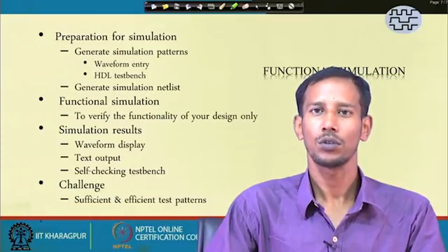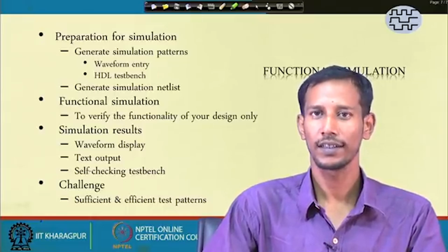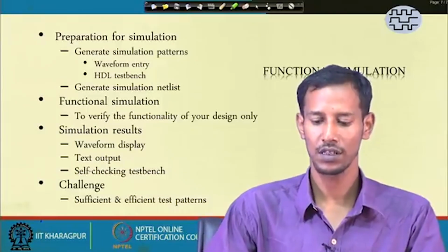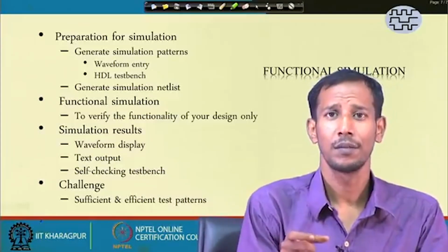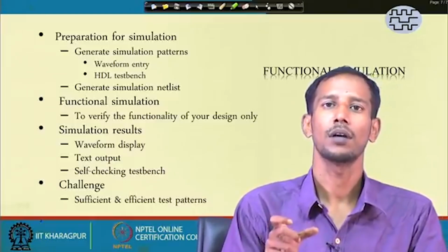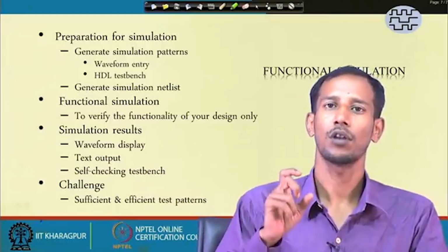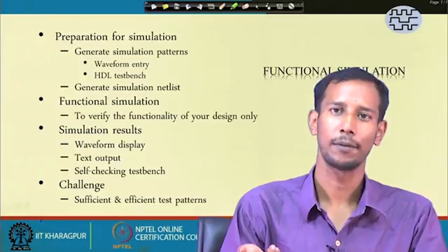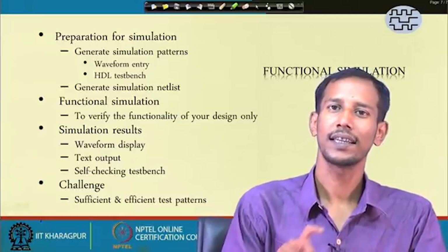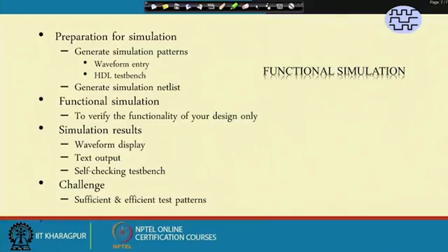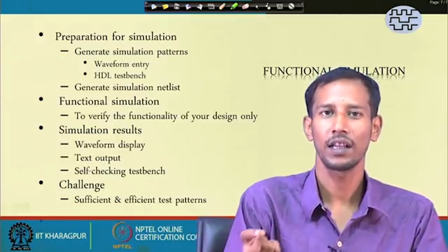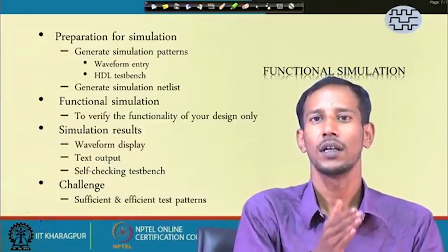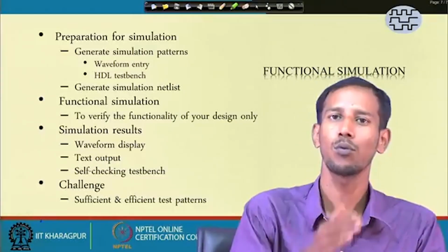So, why do I need to know about this simulation or functionality checking of the particular system? Whenever I have described the system using any language, I have to check it. Suppose I have built one circuit for an adder. By mistake, if I make a mistake and miss something somewhere while describing it, it may become a subtractor, or it deviates from the functionality of the adder. So, at that time how do I know?